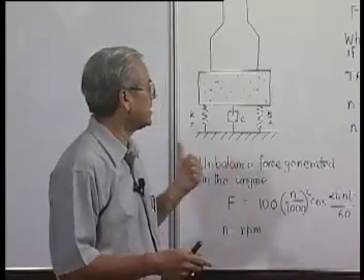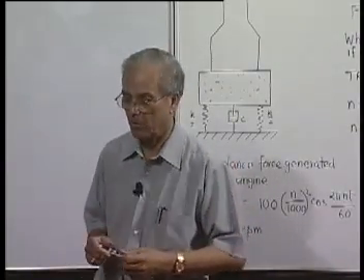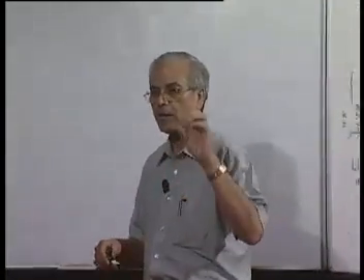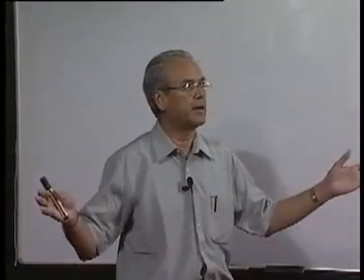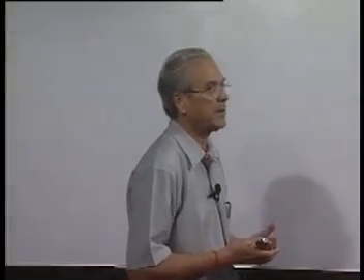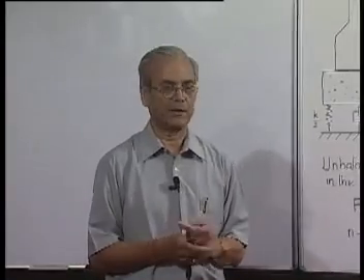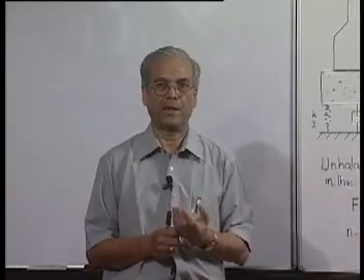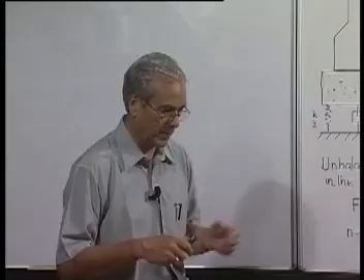We can split the non-harmonic but periodic disturbance into a series of harmonic disturbances. And as the systems we are discussing are always linear, we find the response of the system because of each harmonic, and the result will be the sum total of everything. So what is really happening is a mathematical exercise rather than any physical or mechanical activity.